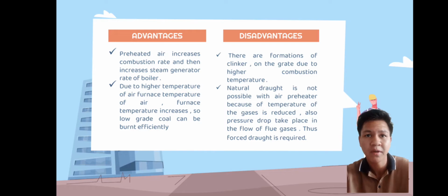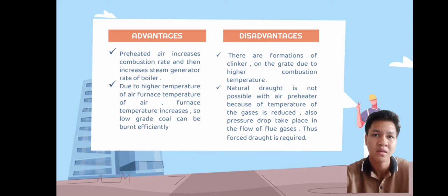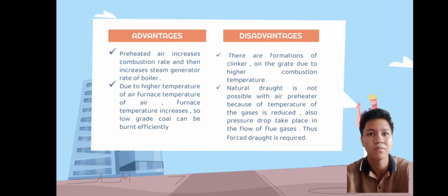These are the advantages and disadvantages of the air preheater. The advantage of the air preheater is that preheated air increases the combustion rate and then increases the steam generation rate of the boiler.